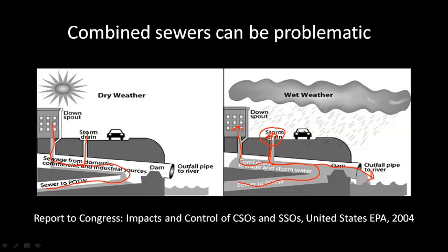And that's why there's definitely a trend in a lot of larger cities to create separate storm sewers and sanitary sewers, so that after rain, there's a dedicated storm sewer to handle that amount of water, and maybe even a dedicated water treatment plant to handle that much water, so that you don't risk having a backup that then leads to sewage getting dumped into a natural body of water or backflowing into a house or out of a storm drain.